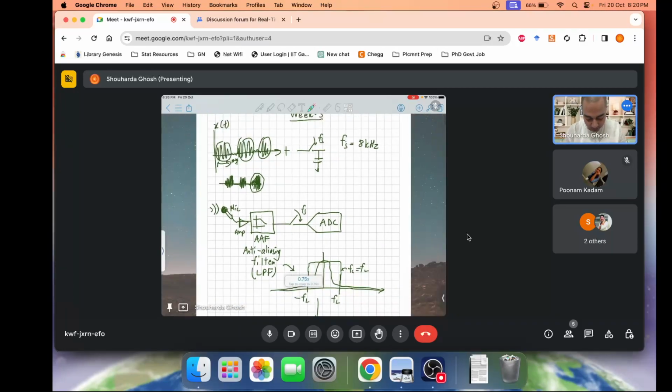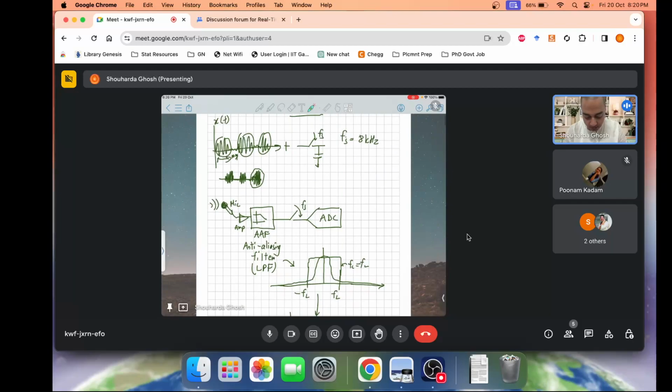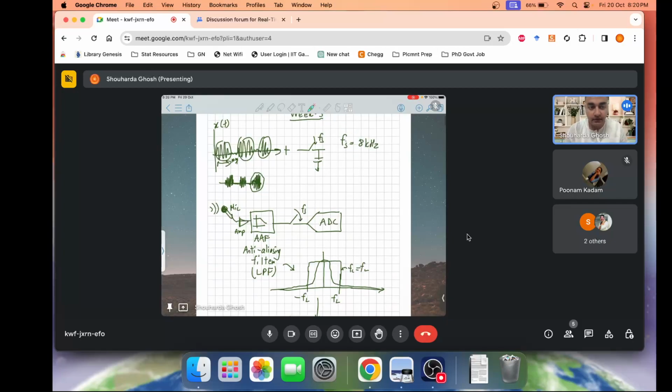Basically, we were discussing problem solving methods. There's an audio signal. When you have a sampling system, a sampler followed by an A to D converter, an ADC actually contains a sampling circuit as well as a quantizer. Before that, you have to ensure that you sample at the Nyquist rate.